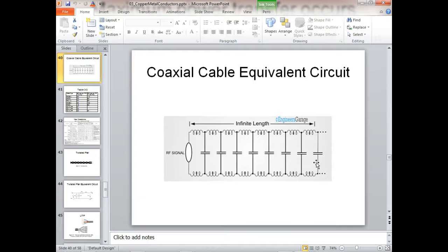Now what we can't do is compensate for the resistance of the cable. So the loss we get in the cable is basically because of R, not because of the impedance in the cable, it's because of R in the cable. So we still have to amplify this, right? Y'all understand? But all your amplifiers are matched to the what? To the impedance of the cable.